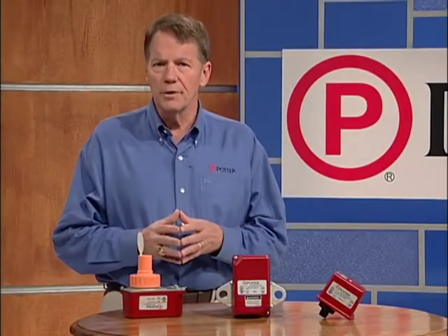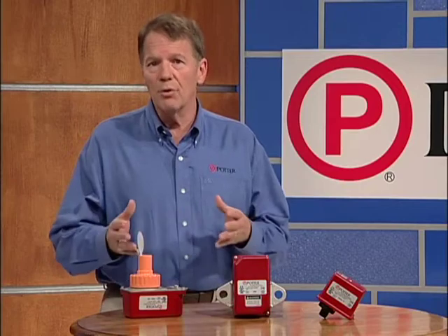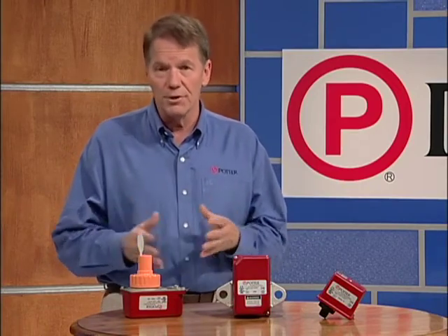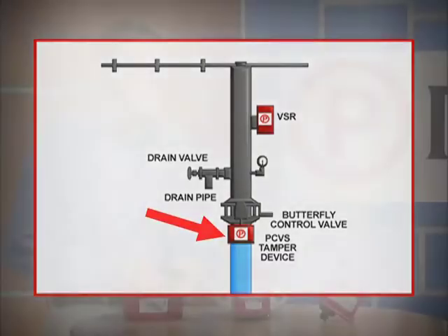All Potter retards are adjustable from 0 to 90 seconds to allow for natural fluctuations in water pressure without triggering a false alarm. Straight pipe risers don't have an alarm valve, but they do have a main control valve and either a riser check valve or backflow preventer. All control valves should also be installed with a supervisory or tamper switch.